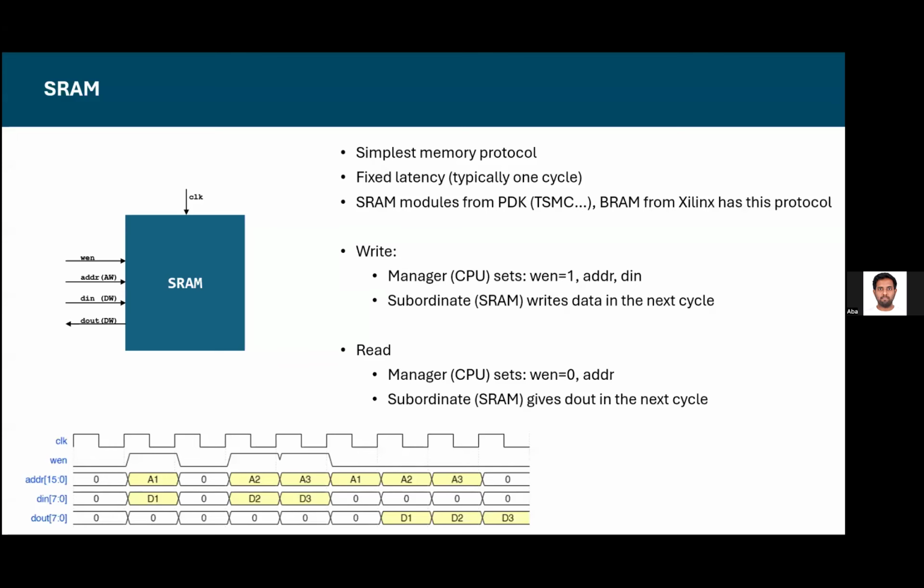All right. So the next one is basically the AXI protocol. So we are going to introduce full AXI, why full AXI is designed that way, and stuff like that. Full AXI is a memory mapped protocol, right? That means you actually have memory signals, you are reading and writing to memory. So you have addresses and all of that. To build towards AXI, we will start with the simplest possible memory protocol, and from there we will gradually see why different things in AXI are necessary.